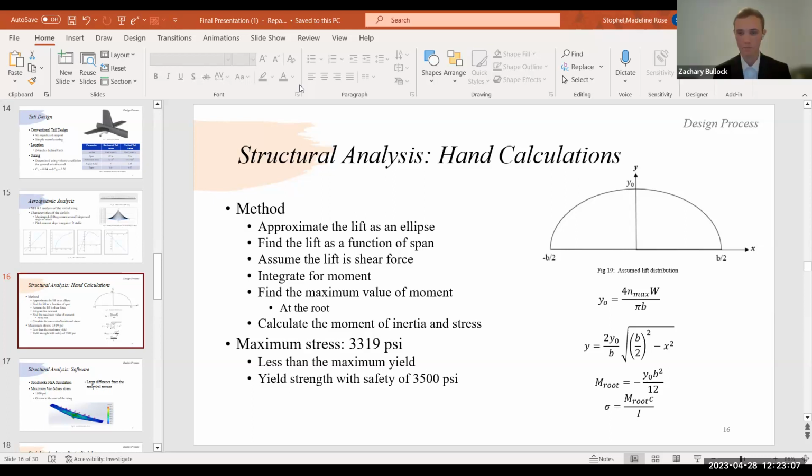Yeah. It would also be nice to see maybe some shear calculations due to the fact that the stuff is printed the way it is. The bending stress is usually just normal stress, like sigma 1, sigma 2. It doesn't really consider the shear stresses acting on the wing as well. And also combined loading from the drag as well.